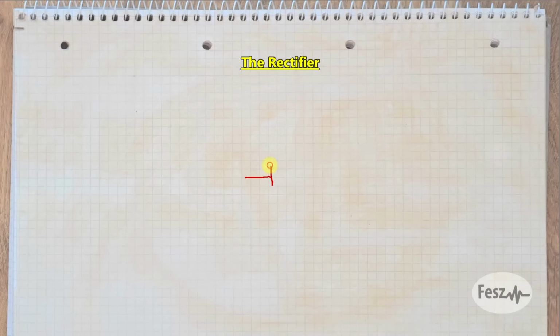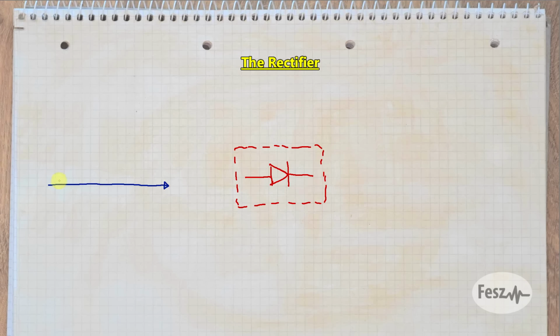So, it is possible to use a diode like a switch and control it using the signal that actually needs to pass through it. But is it possible to separate the control and the useful signal? As we've already seen, if you take a diode in series and apply a 0-volt centered sine wave, then only half of the waveform passes, while the other half is blocked. This is useful when you're trying to rectify, but it's quite problematic if you wish to maintain an unaffected signal.